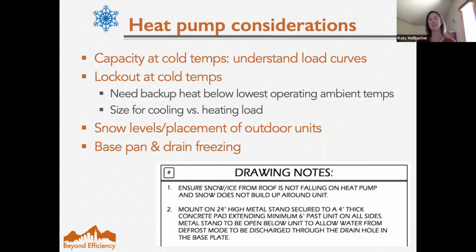And at that temperature, the output of this unit was only going to be about half the load. I mean, it's sort of mechanical design 101, but it's really easy for those basic things not to happen. So, understanding the load curves is important. And then below a certain temperature, the cold climate versions generally will go down to about -13. Below that, they just basically stop working, Kara? Is that what happens?